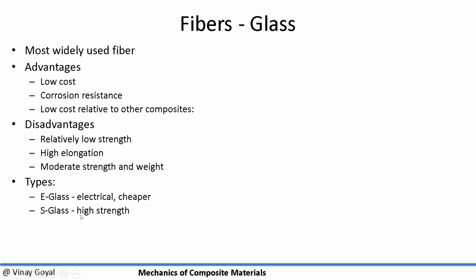And the idea here, guys, is when you're tailoring a particular system across the board, what you want to do is get the best performance and the best application. For example, if I really want a fiber system to get you better electrical conductivity, then E-glass makes sense. And that's what you want to do. You want to balance cost, okay? You don't want to go crazy just because composite sounds cool and I have a surfboard I want to make. I don't want to go with IM7. Who is going to buy a surfboard that costs like 20,000 grand? Maybe there'll be some that will do that.